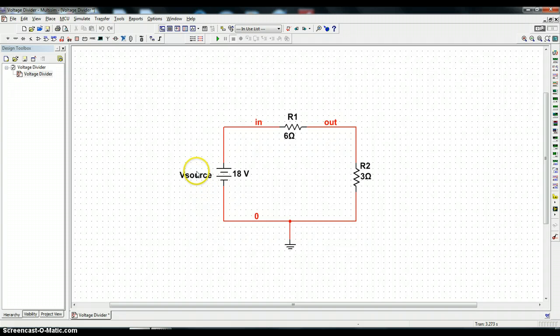Now there are two ways to do the analysis that I'm going to do next. This particular analysis in this tutorial will involve the DC operating point analysis. That particular name comes about because of the original primary mission of the SPICE program when it was first developed many years ago. There was a DC analysis to determine DC variables in the circuit, and then an AC analysis, and since many active devices would be biased at a particular operating point, hence the name DC operating point.